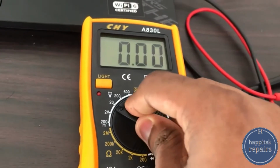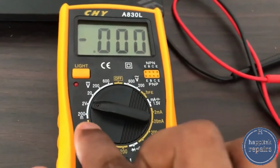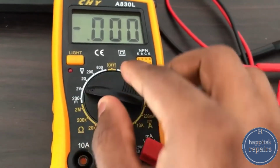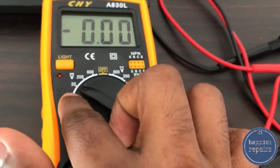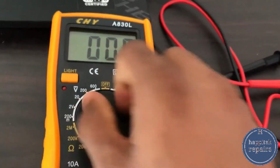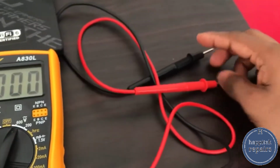So if you want to measure DC, this is the 2 volt range. Supposing you are measuring a small voltage like 1.5 volts, you can use that. If the voltage you want to measure is almost 20, you can use the 20 volt range. If you are measuring something greater than 20, you can use the 200. The same goes for the 600, depending on what you are measuring.